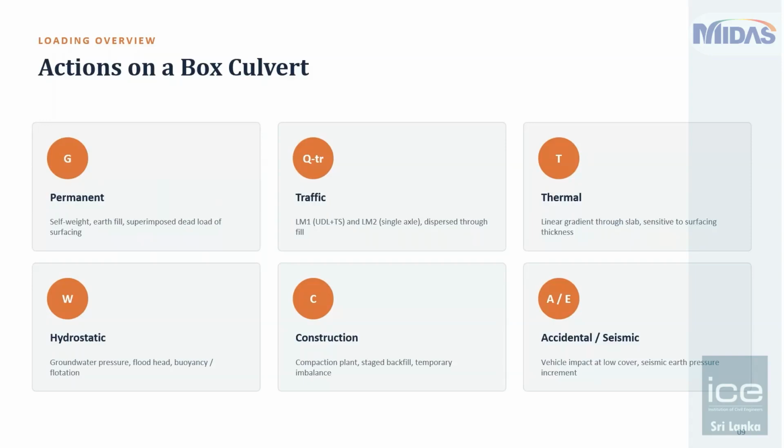So generally when the depth of these is decided, it is assumed that you take the base slab below the scour depth, or you improve the soil so that the scouring is not critical at that level. Okay, so we also have construction staging loads. We'll discuss this in today's demonstration. We'll probably not cover the construction stage loading as well.